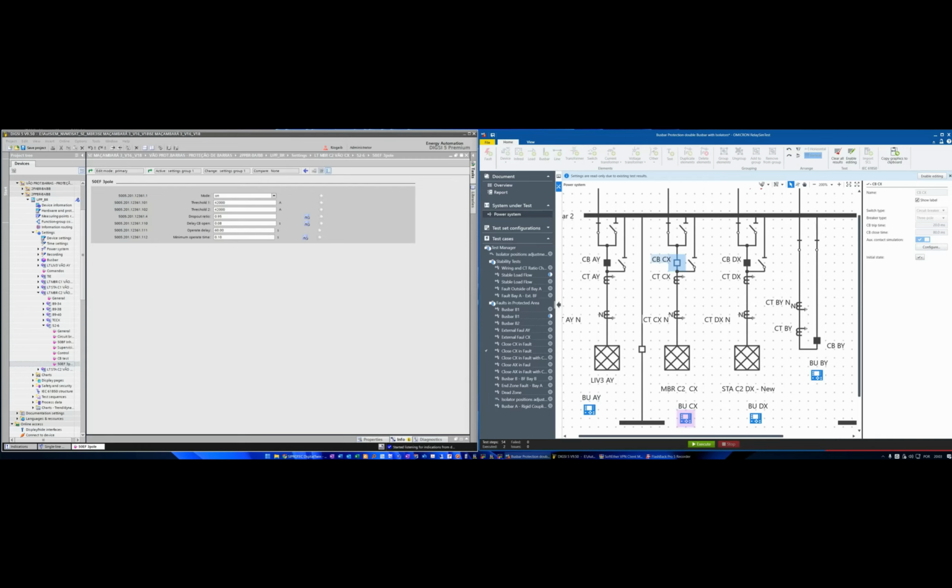When I energize the remote terminal, I have a current that will flow to these CTs. And probably I have a protection in the remote terminal, a switch on to fault, that will operate and clear this fault.